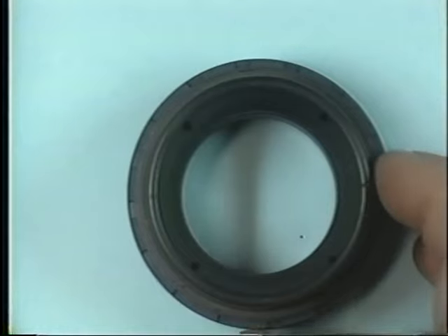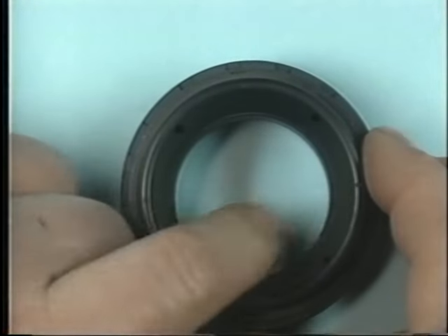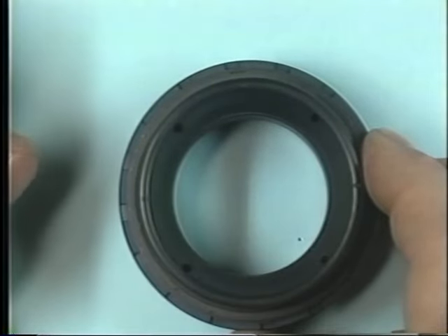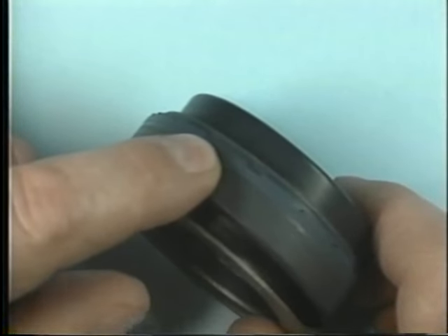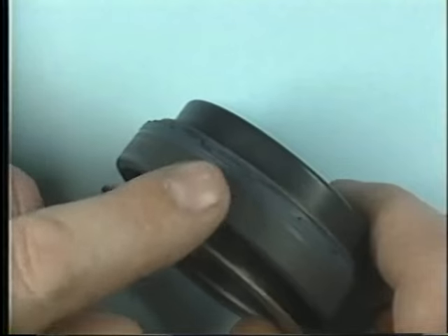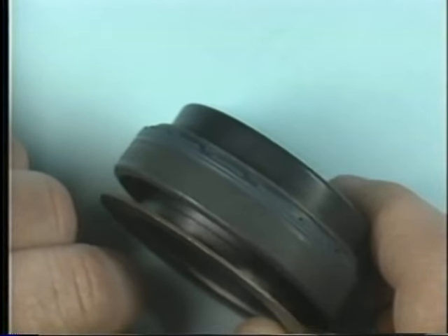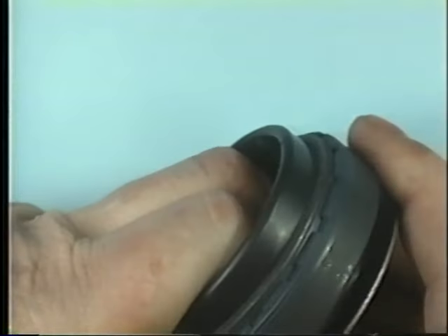So, on this particular setup, we're going to have 3 separate seals here. Obviously, we're going to have a seal on the inside that's going to seal against the axle shaft itself. Another seal on the outer edge seals to the housing. And then, these being 2 separate pieces, we've got a seal in between the 2 of them. And what that does is allow this inner portion here to turn with the axle shaft.